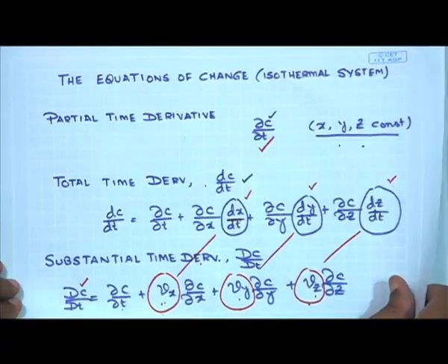for a system with a Cartesian coordinate system, where the dimensions of the volume are del x, del y and del z. So it's a box whose dimensions are del x, del y, del z. It's placed in a flow and the liquid is coming in through the x phase, y phase and z phase. Liquid enters the control volume, and through the phases at x plus del x, y plus del y and z plus del z, the fluid leaves the control volume. As a result of this, there is going to be some amount of mass accumulation, if possible, within the system. So we are going to write the balance equation for such a system and derive the equation of continuity.